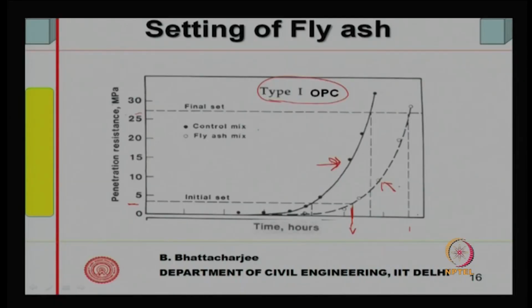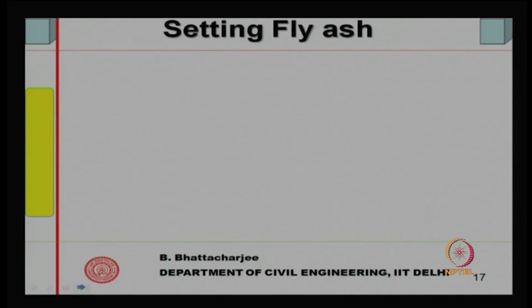In other words, initial setting time is not shortened or reduced by addition of mineral admixtures like pozzolanas, pulverized fuel ash, or just fly ash as they are, or silica fume, but final setting time in a few cases can get elongated, but usually does not extend beyond 10 hours. So, not much adverse effect is seen as far as setting is concerned.